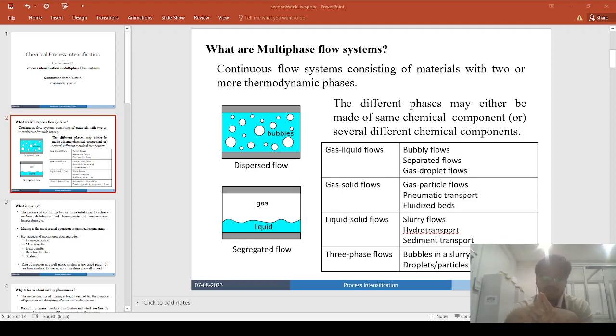Now the reactive separation units may also be treated as a kind of multifunctional reactor in which the functionalities of several processes are combined to generate a new reactor concept. So that is the crux behind performing process intensification using the reactive separation technique. Now out of all of these, the three most important examples of reactive separation processes are reactive distillation, reactive absorption, and reactive extraction. So these are the three very important reactive separation processes.